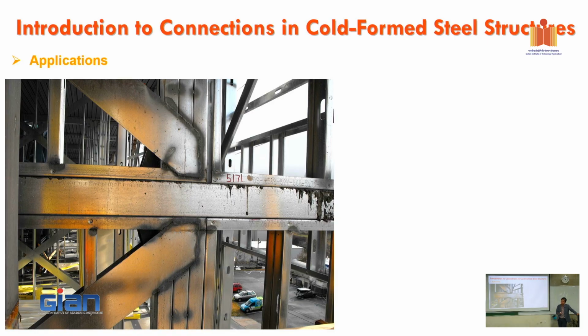Yeah. Any idea what the maximum thickness of cold-formed steel is up to which a screw will be effective? Very good question. I did a lot of tests for high-strength steel, and I found that 3 millimeter is a little bit tricky. It can go through the first 3 millimeter, but if you go another 3 millimeter for the second layer, we tried and it failed a lot; the screw doesn't go through. So it's quite challenging, but in practicality, you can use up to 3 millimeter. Yeah. Our studies indicate that up to 2 mm, screws are maybe okay.